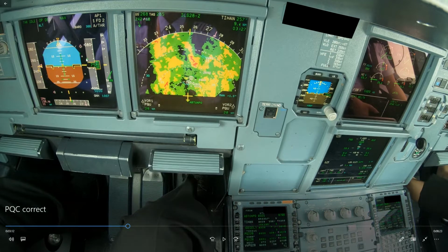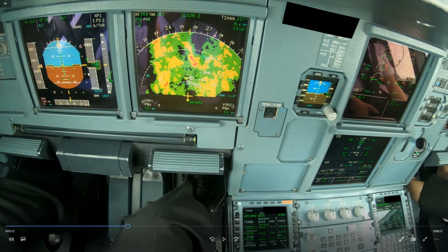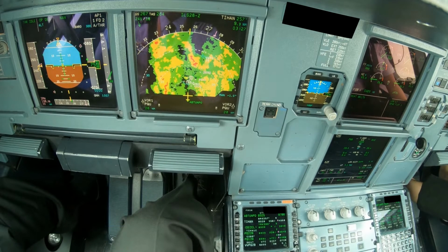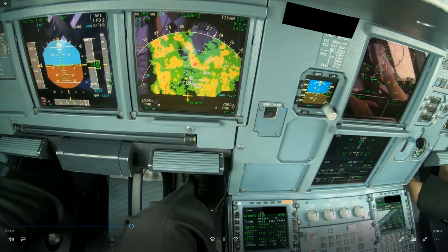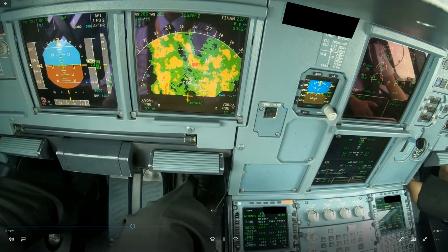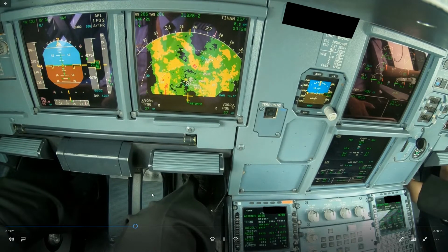You can see that the aircraft is on the VDEV profile. This is not always correct. Sometimes it is, sometimes it's not. It's just a clue, so we definitely have to keep an eye on it. Okay. Now, next what will happen, we start to slow down from 250 knots to green dot speed once we pass 5,000 feet.